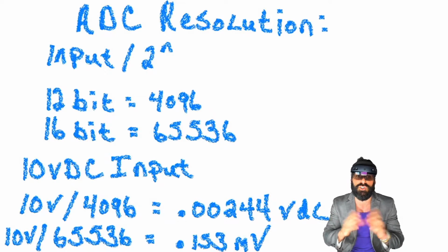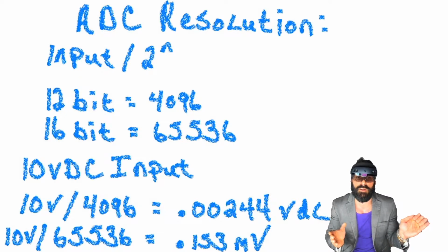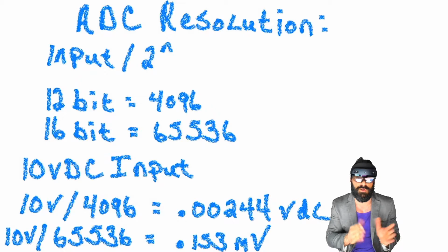An ADC is going to transform an input analog voltage to a binary number, a series of ones and zeros, and then to a digital number, base 10, for any kind of battery monitor or UPS, power system inverter, anything that's being fed into a BMS or a supervisory control and data acquisition system. Now this number of binary digits or bits is going to represent the digital number that determines the ADC resolution.